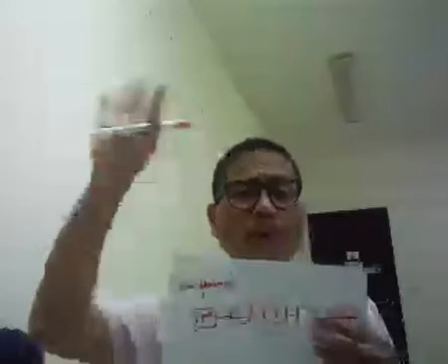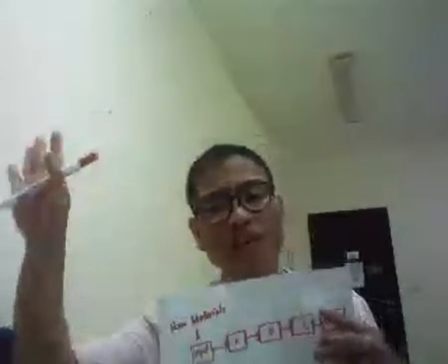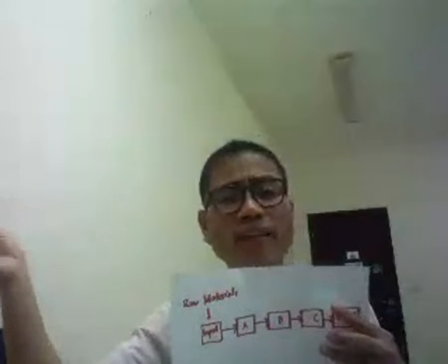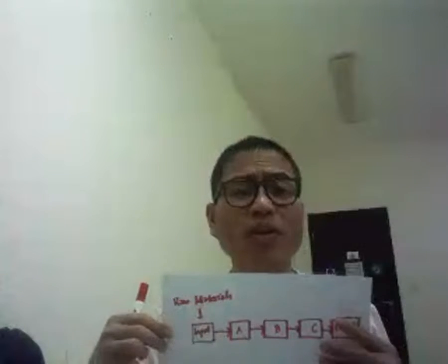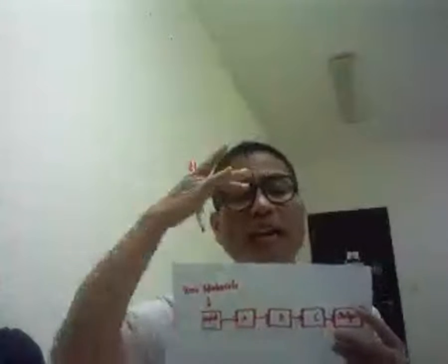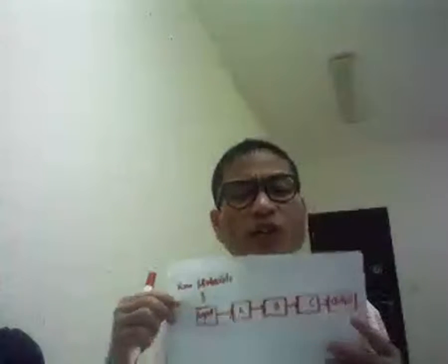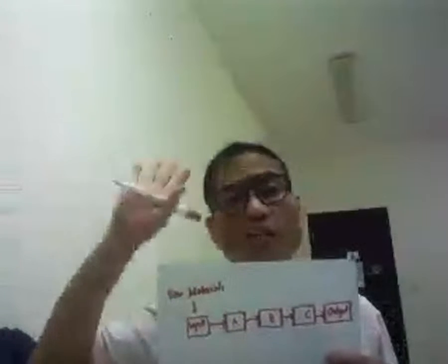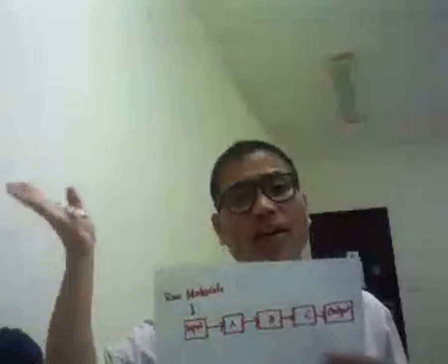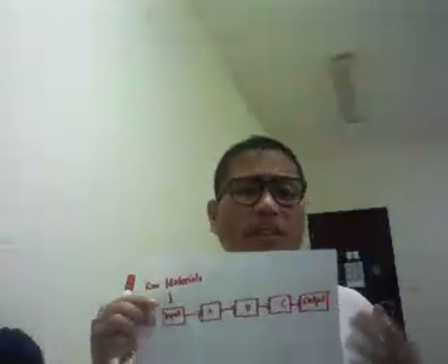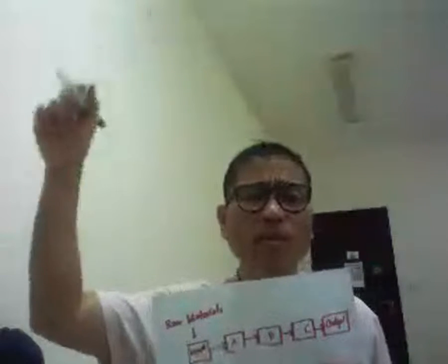Then in your process hazards analysis, you need to have a column there. What you observe, what could go wrong, what are the abnormalities, what are the possible hazards in each process. What are the hazards and what are the people involved, who will be affected, and who will take the action to rectify those hazards and risks in each process. And then you need to have also the risk ranking. It could be a low risk, a high risk, and then medium risk, and then until the output. You have to make a column like this.